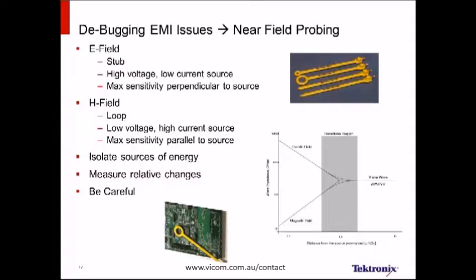Now, you don't actually have to buy these probes. The probes are fairly easy for us to make, and there are many instructions that we can get off the internet. What I will say, though, is please be careful. When you're putting together your own probe, remember that if it has a conductive surface and you're sniffing very close to the device under test or the PCB, you don't want to cause yourself any issues by shorting out the PCB during your test.